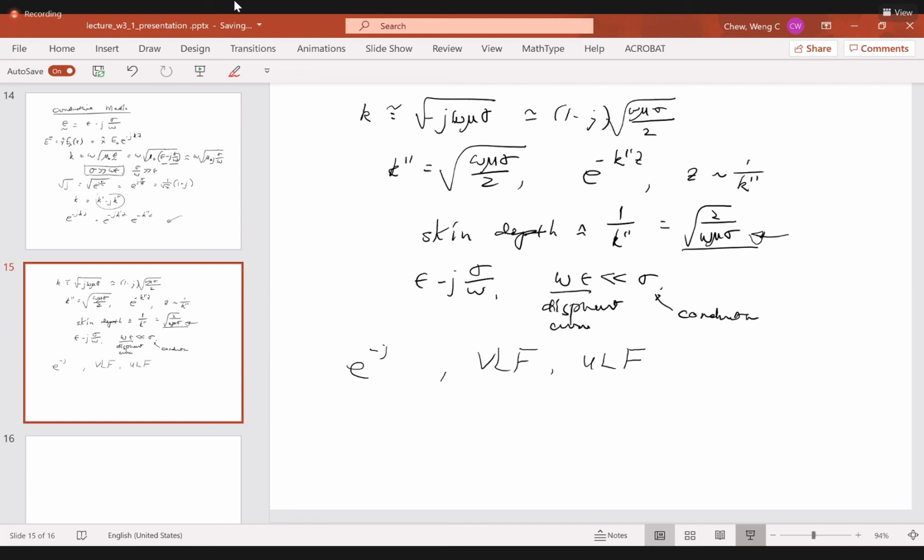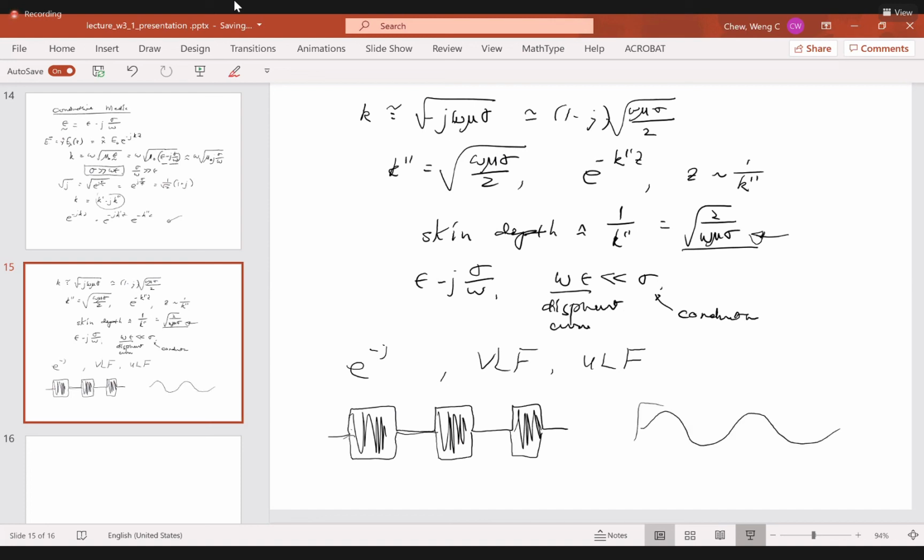Very good. Say if you want to send zeros and ones, you can send them with the carrier frequency. What is done is that you have to use this to modulate on top of a carrier. There's one way you can send it. If your carrier has very low frequency, say if you work in the kilohertz range, your ones and zeros have to be far apart in order to be carried by the carrier. So your data rate is very low.